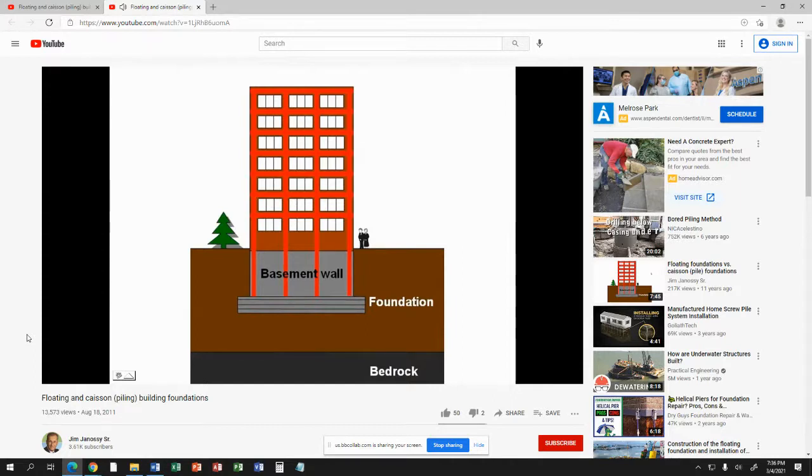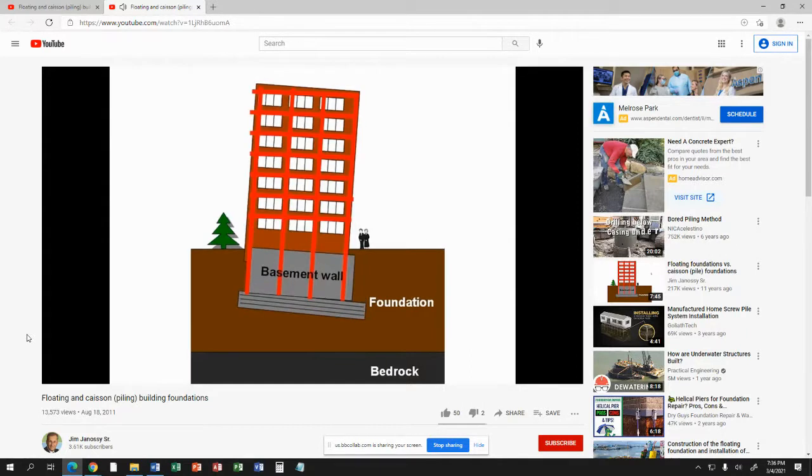However, if they were not very lucky about things, the building might sink something like this, in which case, depending on the amount of uneven settling, things were kind of bad. And you will see some buildings like this. On Michigan Avenue, there's one that has a notable slant to the windows. On Wabash, there's also another. And some buildings attempted to correct for this by making cosmetic changes to the way the window frames worked and hoping that the building wouldn't settle any further.